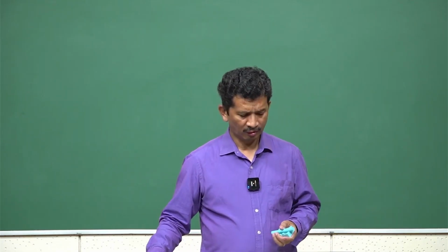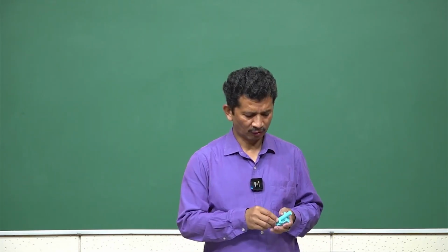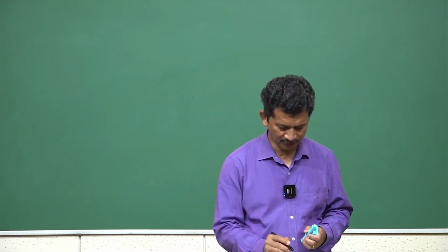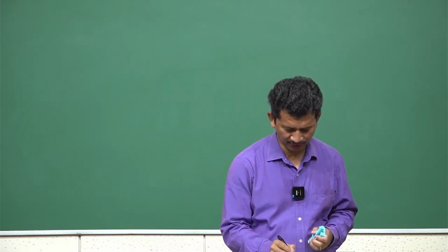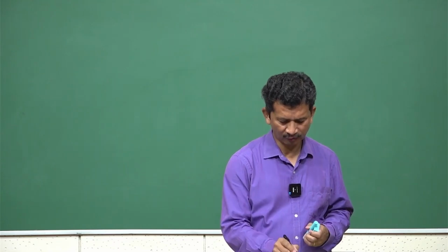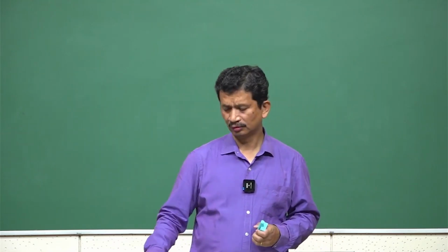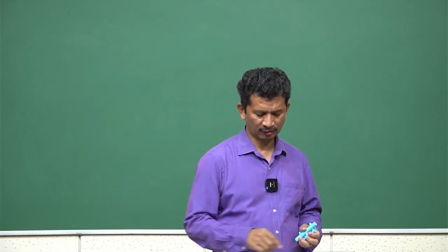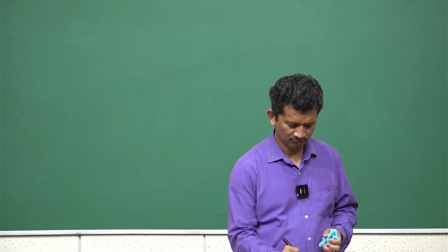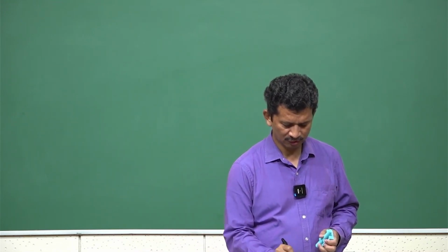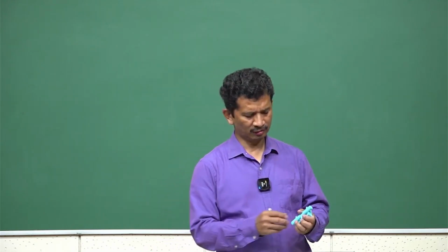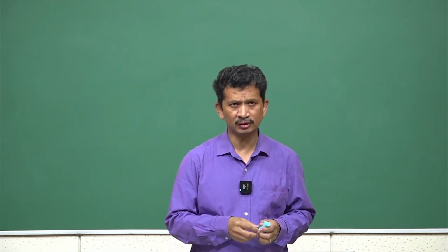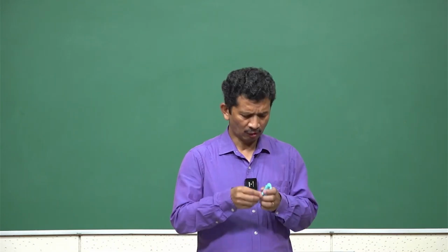But we want to fix it. So, how to fix it? Suppose I just make another V here. Some projection I made and then I made another V. So, I defined another V contact. Again it is a very thin structure, and 2 V's support the bar and another V just locks the position.